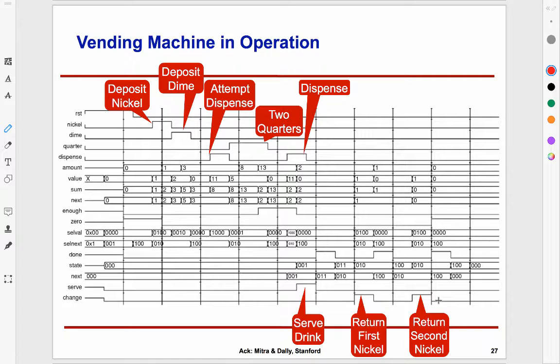These designs can get extremely detailed and messy, and so one has to approach them very carefully, simulate a lot, and stay away from Mealy type designs. I know there was lots of discussion on Piazza on this issue. Mealy machines can make debugging particularly tedious and hard. So just stick with things happening at clock tick. Worst case, all that is happening is you're paying with a little bit more delay in the output.